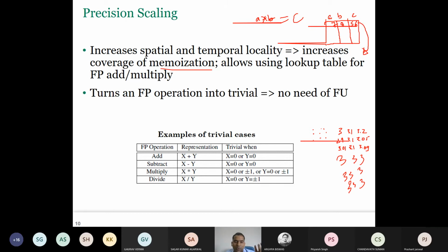It's not that every time you have to compute the log of something, you really do the full expression. You just read it from the log table. So multiplication is somewhat cheaper, but there could be some operations like sine theta, cos theta, tan h or exponential, which are really complex or time consuming. So instead of all the time computing them, you can compute them once and store their value in a table. That's called a lookup table. And instead of doing those operations, you can use those values.